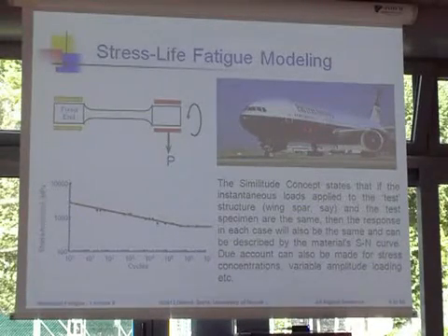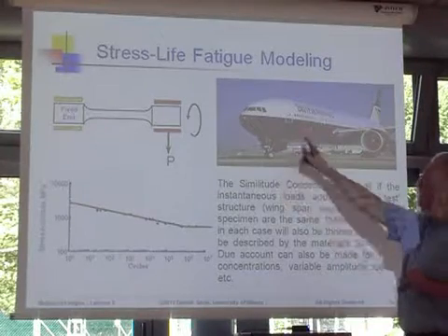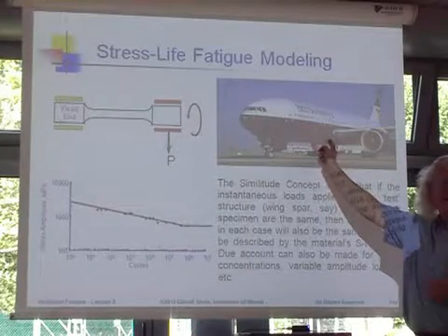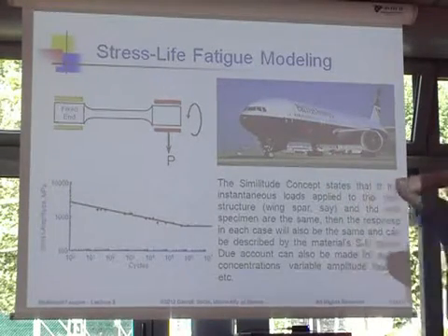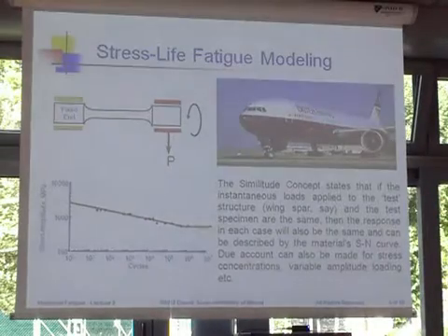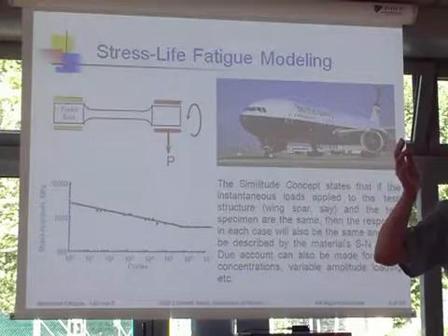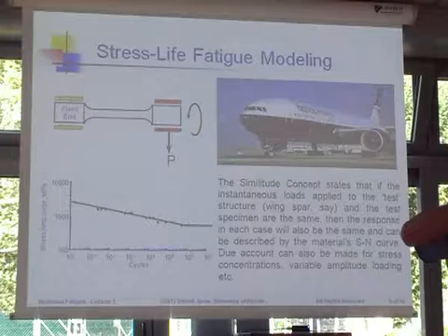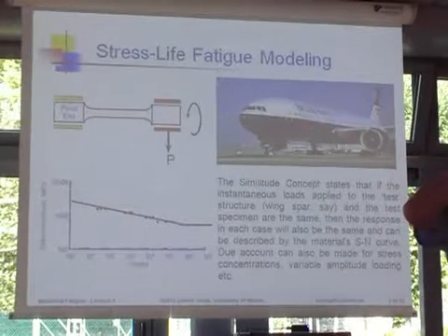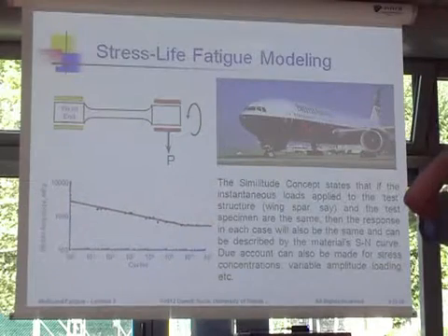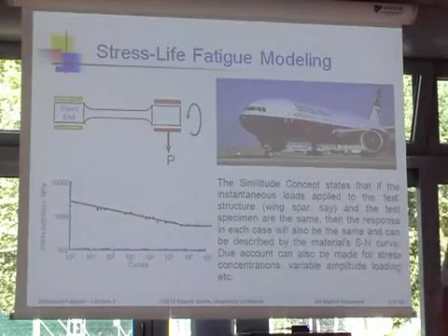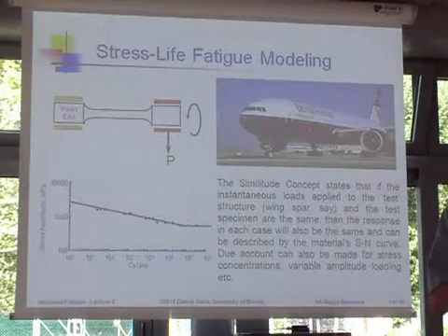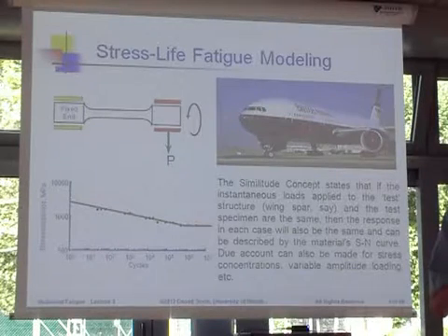Yeah. You asked another question. Is this a good model for the airframe? Probably not, right? So if I think about the size of this airframe, and I think about all the little cracks that are there around rivet holes, and I think about cracks that are there because when they manufactured it, they pulled a little bit too hard, and so on and so forth, it's a terrible model.